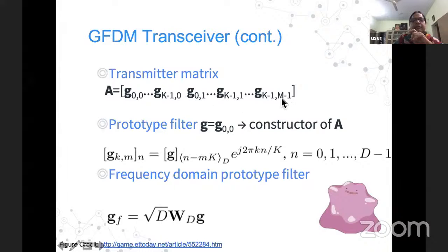What is the difference from OFDM to GFDM is that on K subcarriers, we are sending the same data symbol 0, 0, 0. Again, on the next K subcarriers, I'm sending the first symbol repeatedly. And at the end, for the Mth subsymbol, I'm sending on K subcarriers. I'll show you the exact diagram.